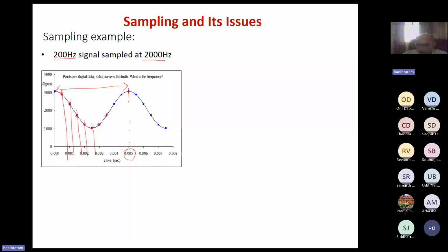But finally, why am I doing this analog to digital conversion? Because your embedded system or embedded processor does not understand the analog signal. It can understand the digital signal. So that's why I am converting it. And after converting, suppose I talk about the filter. If I talk about the analog filters, like what we have discussed, low pass, high pass, band stop, those filters take some analog signal as input and then do the filtration. So what kind of filtration? They are removing some unwanted frequency components, right? And then at the output, they are giving the filtered output, which will be a kind of noise free output, right?